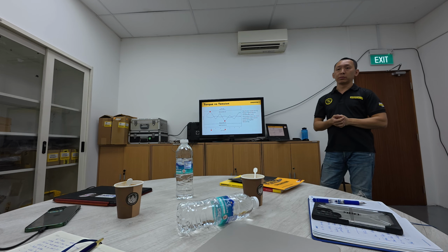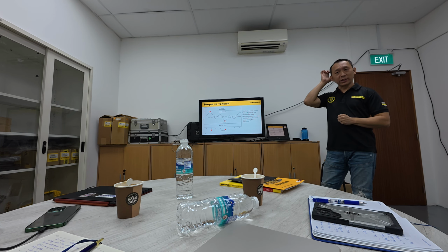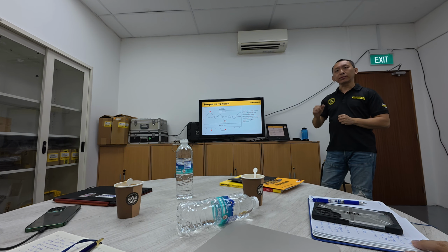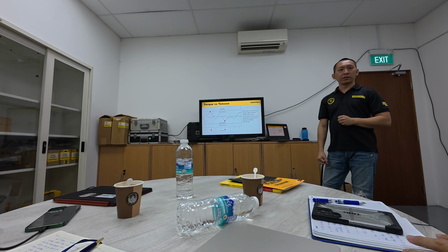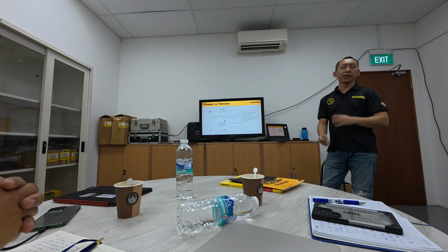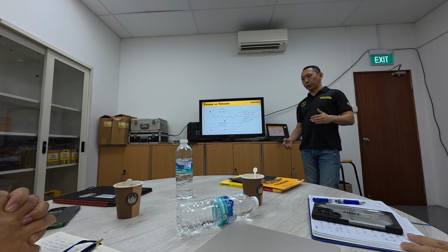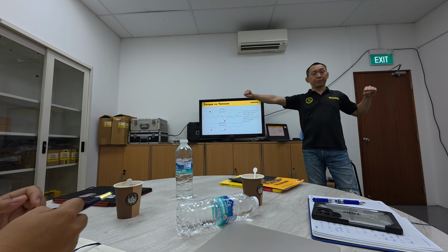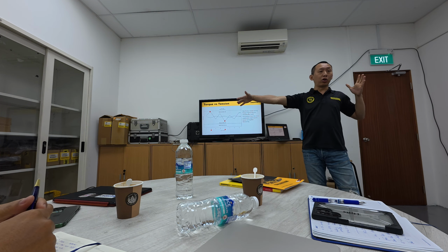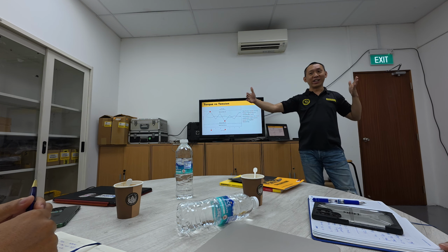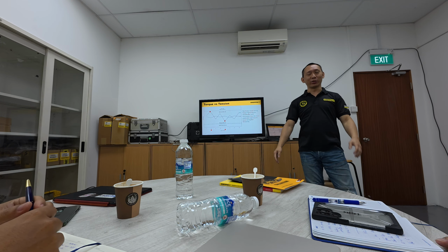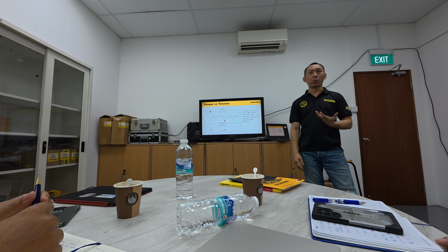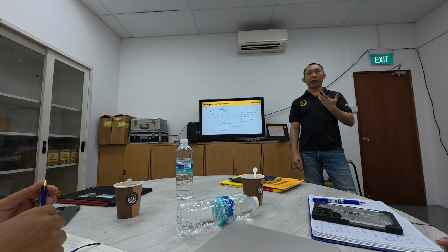The tensioner pulls the bolt and then you turn the lock nut by hand. When you do such an application, you need a long stud, and not all places have that kind of space allowed. So it really depends on what type of application.